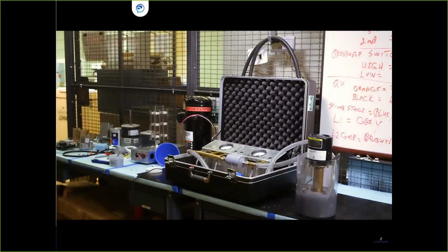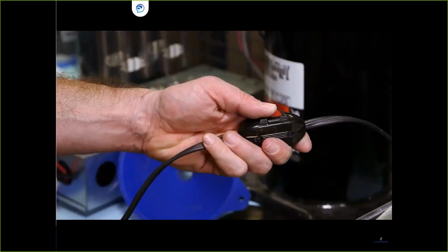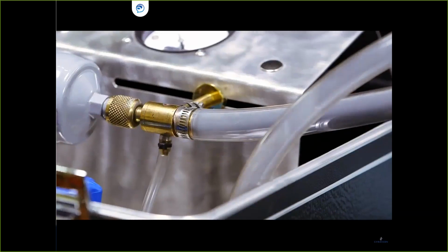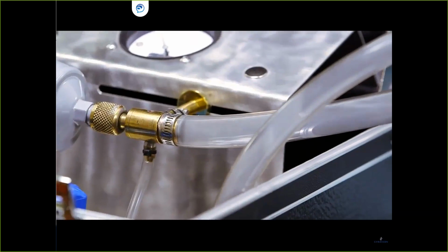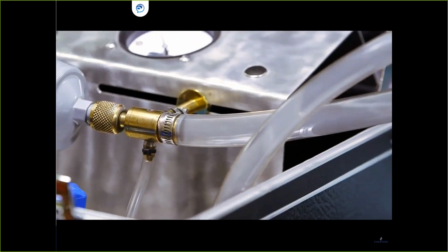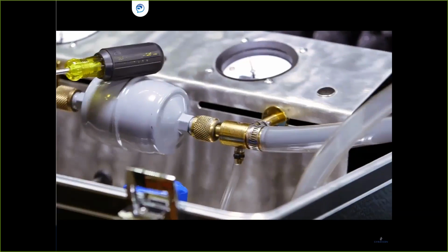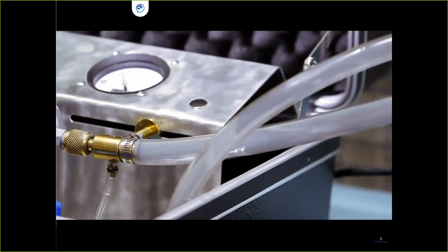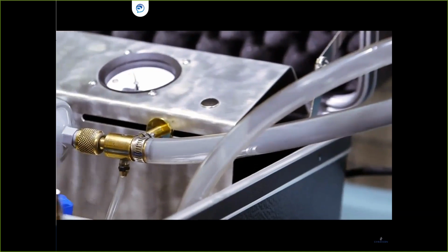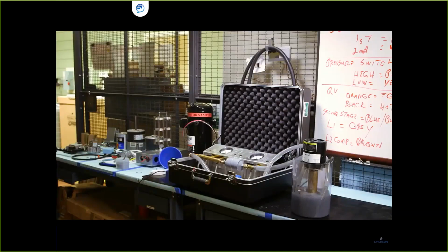Now we're going to simulate system cycling. Notice that upon startup, you see the release of contaminant back into the system. You can demonstrate the effect of normal system vibration by tapping on the dryer. There's a substantial release of contaminant back into the system. After more than 4 minutes of operation, the system is still very cloudy.